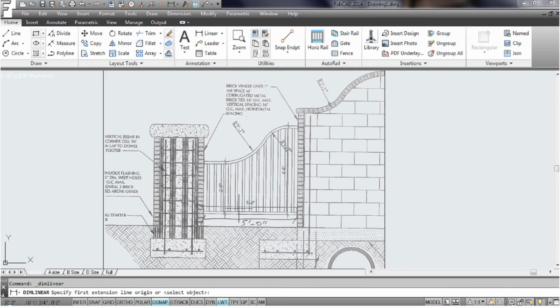Now, unfortunately, this is a scanned PDF, not a PDF generated by a CAD program. If it was generated by a CAD program, we would be able to sense the endpoints and all that. But we're going to have to just be very careful and just point exactly to each end of this. And so right now, this PDF, those dimensions are 1 foot 5 and 5/8. So we got to make it 5 foot even.